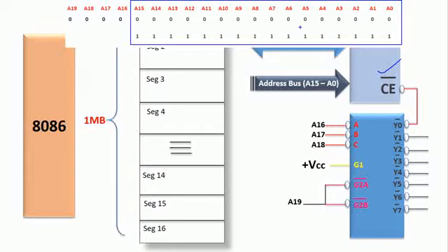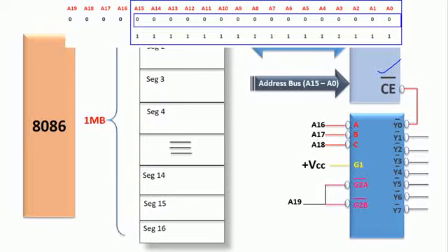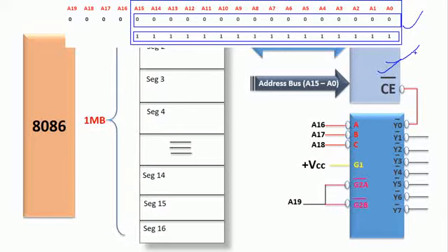And now this bit combination is varying from the minimum to maximum bit position. Minimum is nothing but the 16 zeros. Maximum is nothing but the 16 ones. This is the address range of this memory device, because it is a 64 KB. Now, to which segment it is mapped is the question.